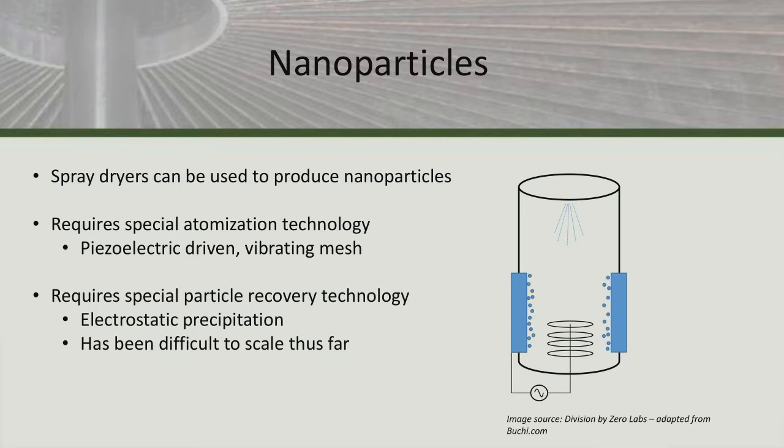So if you're targeting 300 nanometers, for example, you're going to have to use either a filter, a HEPA filter, or an electrostatic precipitator to collect those particles. And you know, the filters actually don't work so good either, because it's hard to then recover. You can trap the particles on the filter, but to recover those particles into a collection source doesn't work so good with nanoparticles.